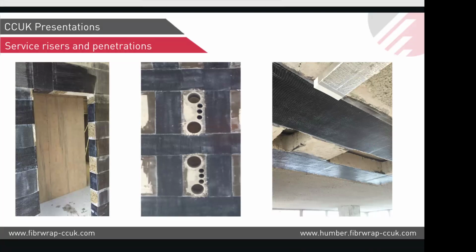The first and most important check you should run is whether, by creating these openings, you are compromising the global stiffness or overall stability of the structure. If the answer is no, the stability is not compromised, then you can use carbon fiber. There is a good chance that you can find a solution with carbon fiber. But if you're compromising the stability, then obviously traditional steel is a better option.